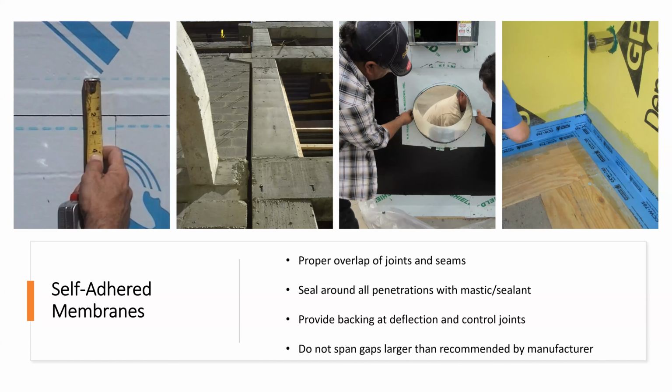So another thing you'd be looking for is someone trying to put this material over, say, a gap of 1 inch, a gap of 2 inches, whatever that happens to be. So we have to do something in regards to providing that backing. So backer rod and caulking. Is it a piece of sheet metal? Is it a piece of whatever else that we can stick in there? Because these things like to be fully supported, okay?